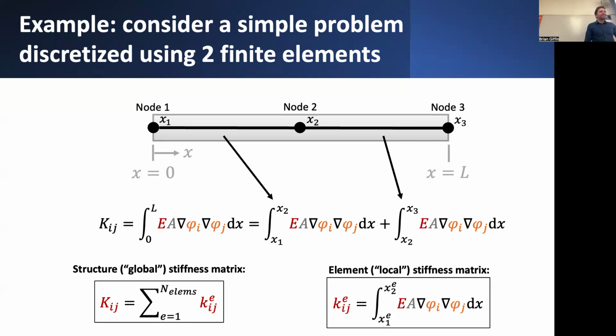But still, we haven't worked around this problem. How do we actually compute these integral expressions over these individual elements? In general, if we have relatively simplistic expressions for the nodal shape functions, or the nodal basis functions, plugged into this expression, maybe it won't look so bad, but we won't know. And in general, we might have some funny looking basis functions chosen for the nodes. I've given you an example of what these basis functions look like, assuming strictly piecewise linear interpolation of these nodal positions.